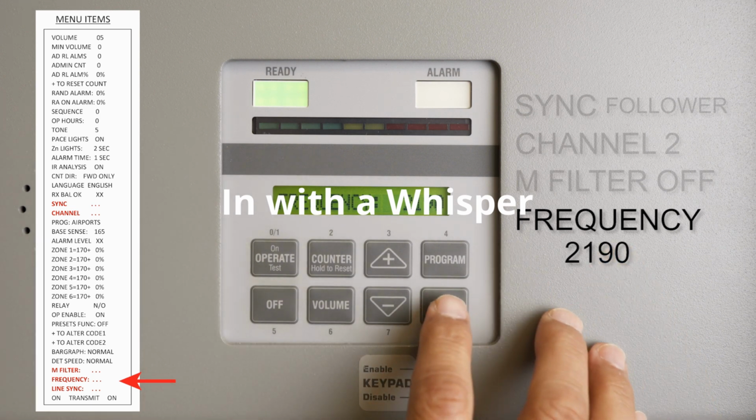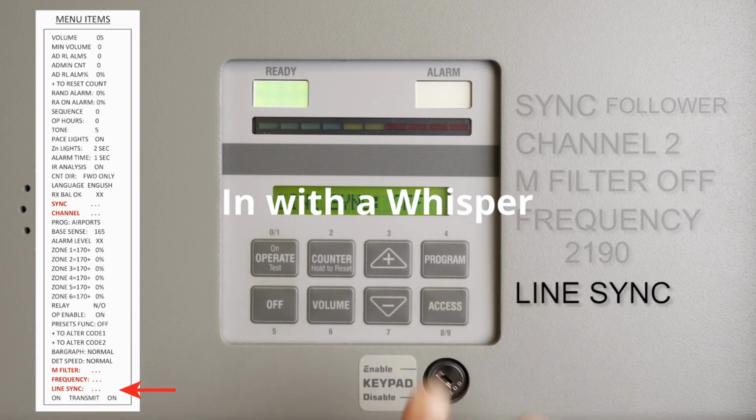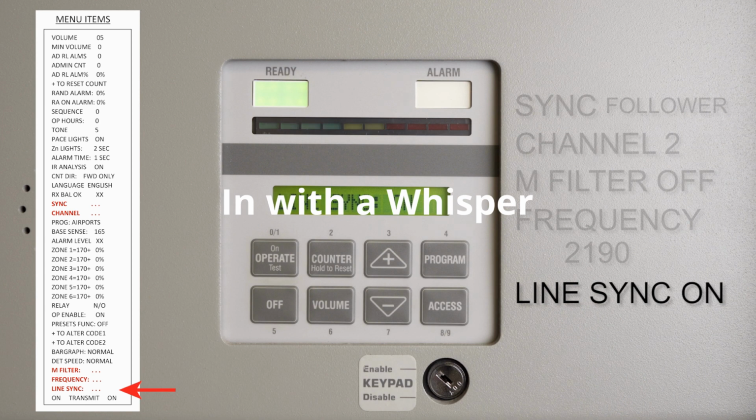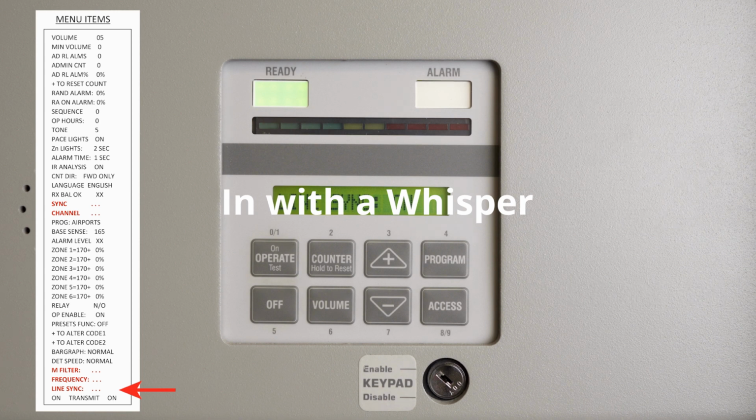Finally, use the Access button to scroll down to line sync. Use the plus or minus buttons to change line sync to on. Changing line sync to on while follower is enabled means the unit will only use follower to sync with the master and not the line from the AC line. This concludes all the menu changes needed to set up a follower unit.